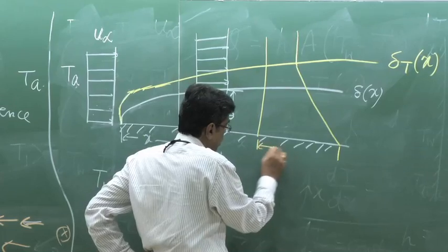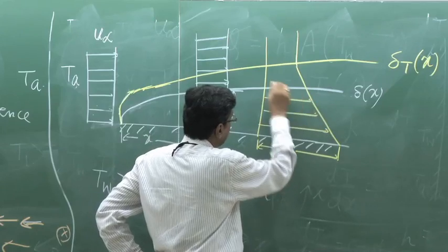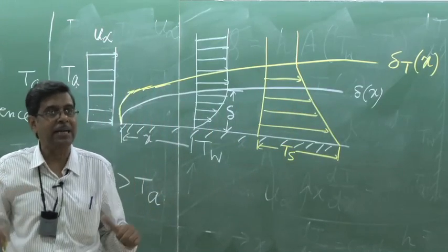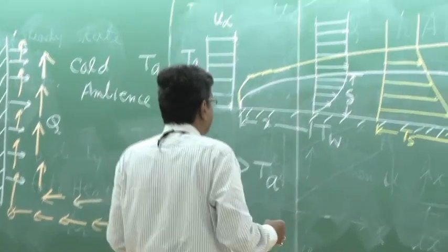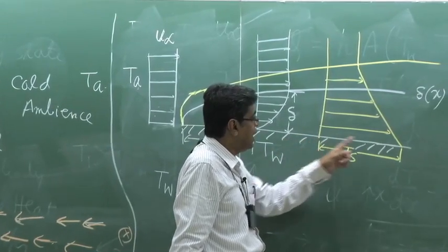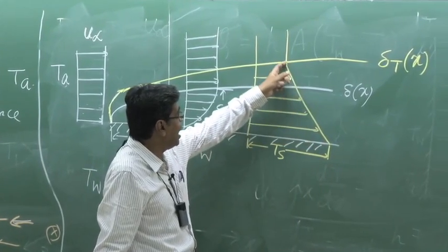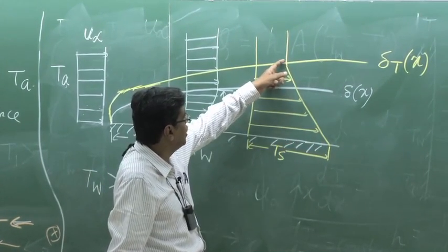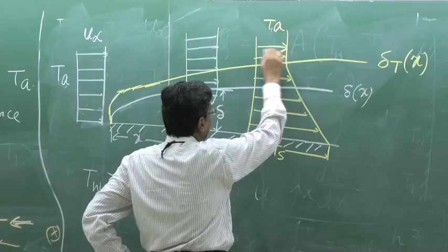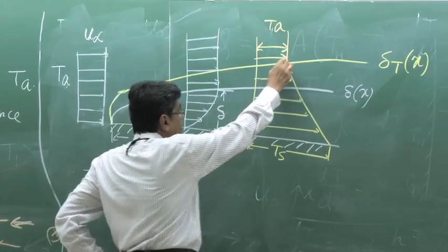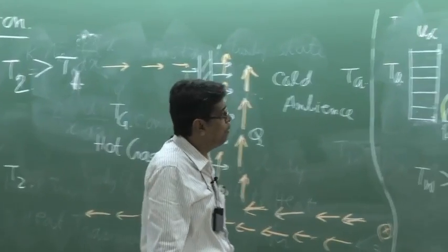So this is your wall temperature Ts, and because of its conductivity and retention capacity by heat capacity, which I will tell afterwards, known as thermal diffusivity, the temperature field is also adjusted in a way that temperature from the surface temperature in the fluid decreases, and after certain distance away from the surface remains constant, and this is TA, free stream temperature, cold air temperature. So this is the picture, the development of the thermal boundary layer.